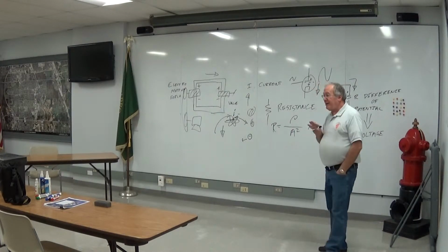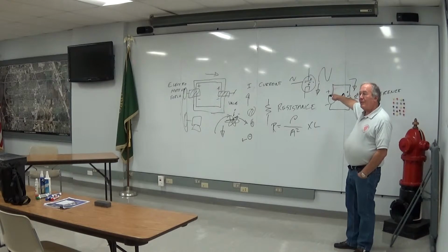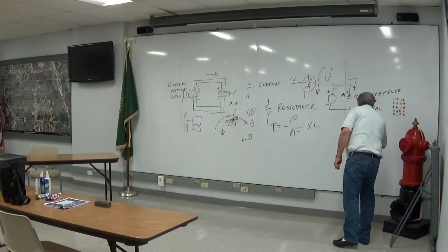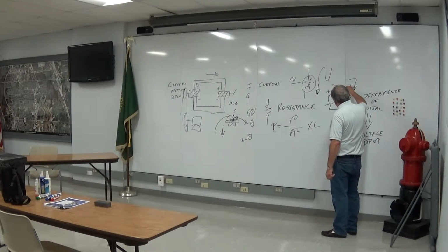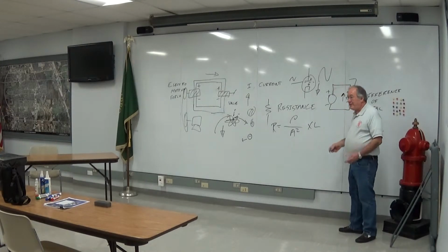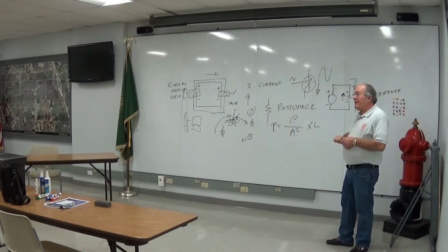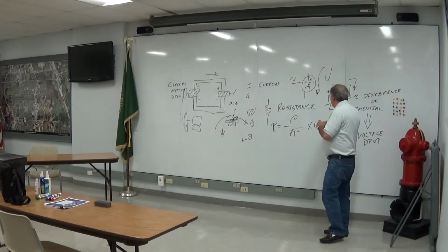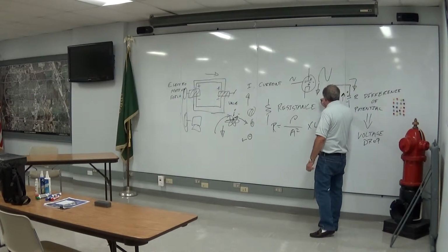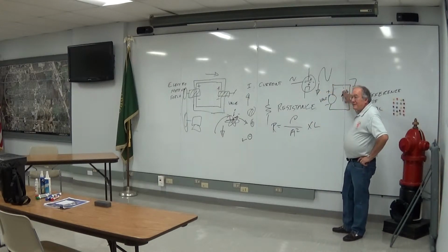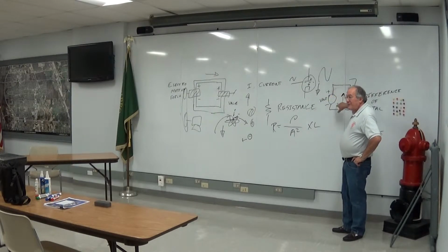So here's what I want you to think. Whenever you see voltage, add a word to it: voltage drop. Because really what it is, the potential difference between the high and the low side. So you don't really think of, even though they use volts to measure this voltage source, it's really an electromotive force that starts the process going. The result is a voltage drop when you push that current through something that impedes the flow of that current.